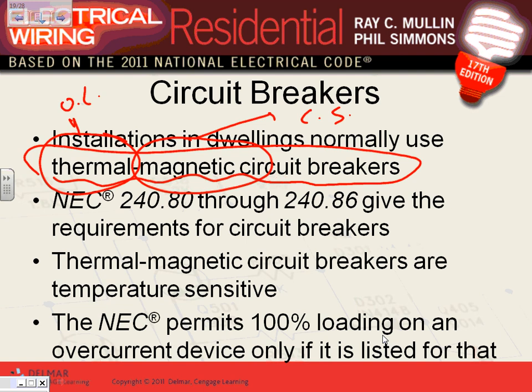Very important, guys. This device is made out of two components, the circuit breakers. Unlike the fuses, where dual element time delay fuses have two components. Unlike the non-time delay fuses, which have one element, if it's overload, it takes time to heat it and break it. If it's short circuit, it heats faster and opens. That's a fuse. Circuit breakers have two components. One is thermal, so two pieces of metal.